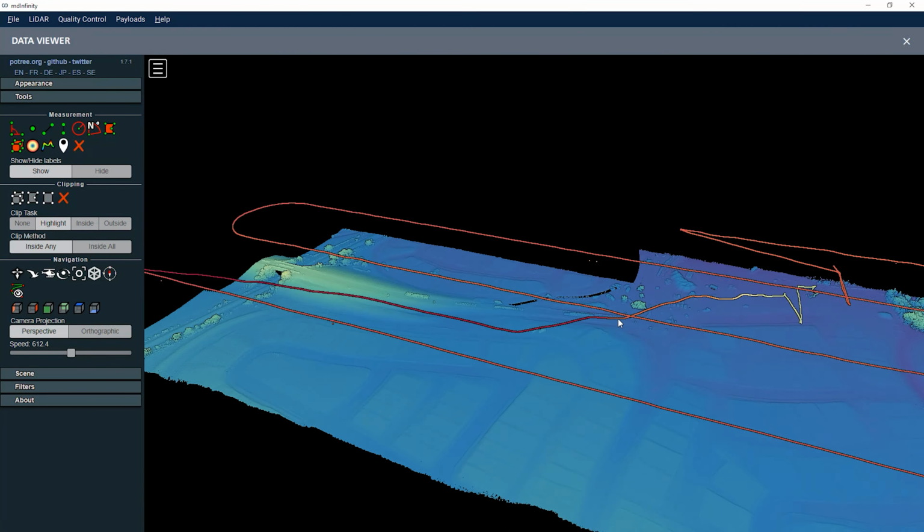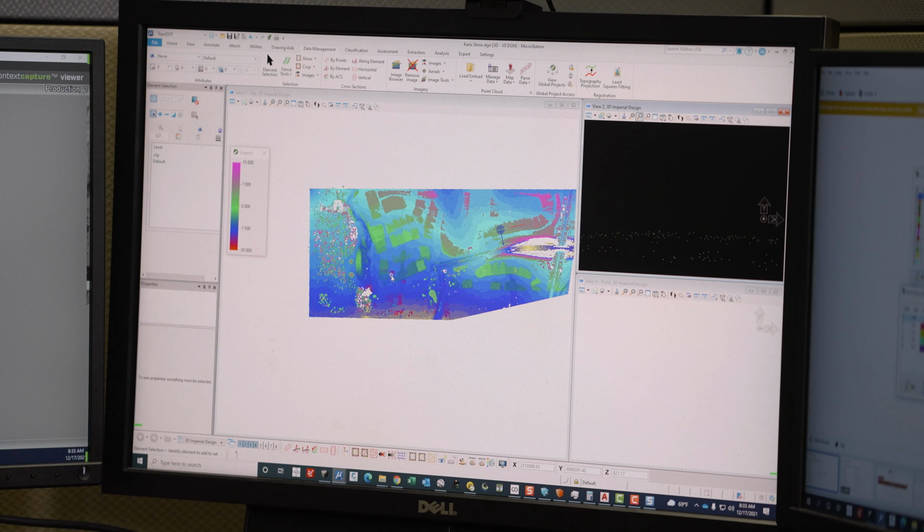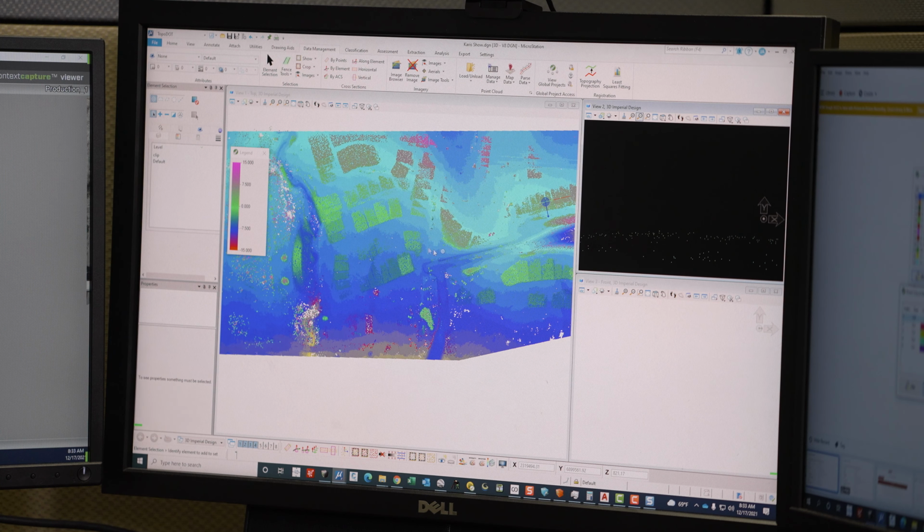We're going to go straight to georeferencing. Once you get your point cloud done, if we leave it rolling here, it takes the better part of maybe 5 minutes, maybe 3 minutes, to process that. To get to this final deliverable, the next step from georeferencing is I've got to extract a surface from that point cloud. What we're seeing in this visualization is distance from a set plane, so I can start seeing some of my pads appearing insofar as what we collected.